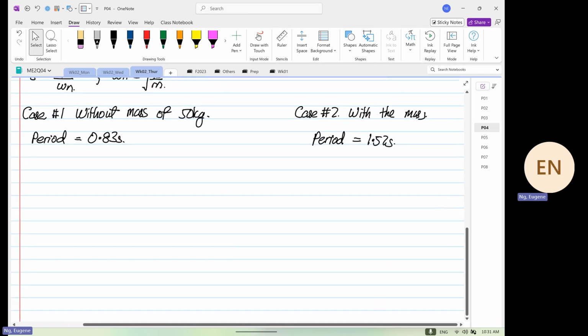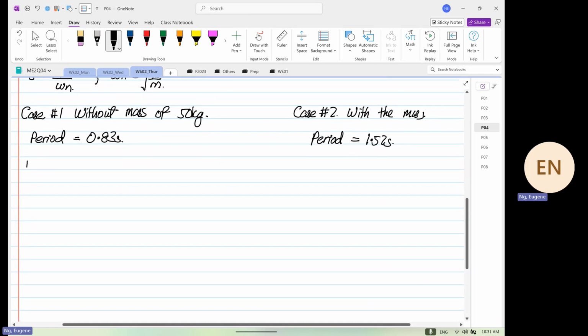So what we're going to do now is construct our free body diagram. And we know we want our system positive to come down. And then we have attached two springs. And if the load were to be coming down, the springs will be under what? Compression. Okay. So this is the reaction that we are going to get, and this is our mass.